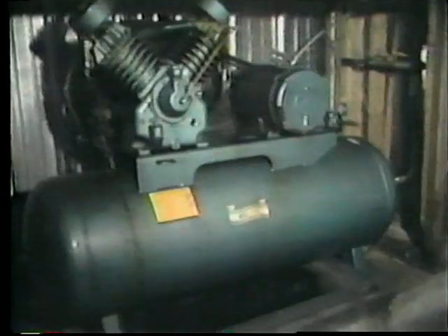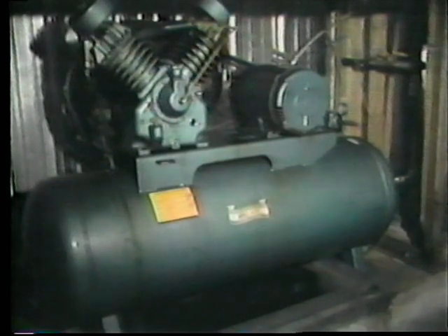A good rule of thumb is that it is better to oversize a receiver than to specify one that is too small. A large tank adds little to installation cost, and because it can average varying load demands, it provides increased capacity to meet demand surges. It also lowers air velocity in the tank, which improves fallout of condensed moisture and solvents or oils which may be carried in the air stream.